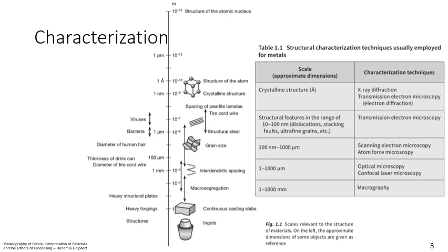The methods for inspecting different features of steel are different based on the size structure. When you're talking about investigating what's going on at the crystalline structure, tools like X-ray diffraction and transmission electron microscopy have to be used. And then as we work our way up to the size scale of our interest for grains and for microstructure, we will be talking mostly about optical micrographs. That's what's going to be most important for our quantitative assessment of microstructures.